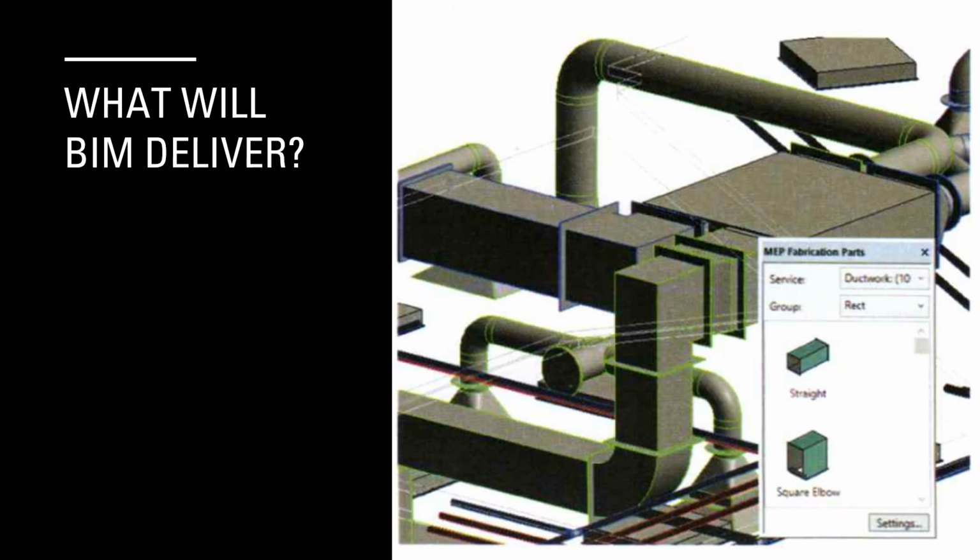Second, BIM enables integration with analysis tools. Some applications connect directly with Revit, allowing two-way data exchange for pressure loss, heating and cooling loads, and more. In other cases, we find common ground, understanding what can be transferred and where limitations exist.